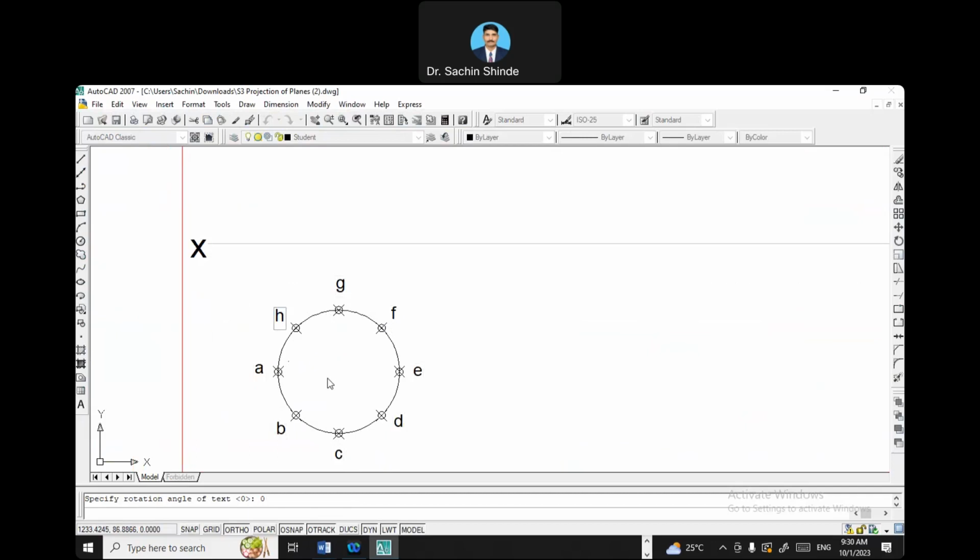And then here you can click at the center and you can mention this as true shape. Now after entering each and every label, click outside this box and then escape. Then only that DT command will get executed. Okay. So now labels are over.